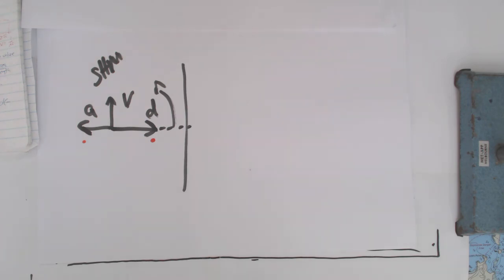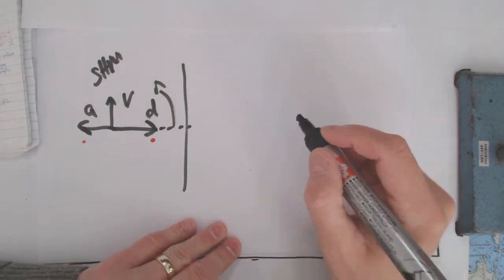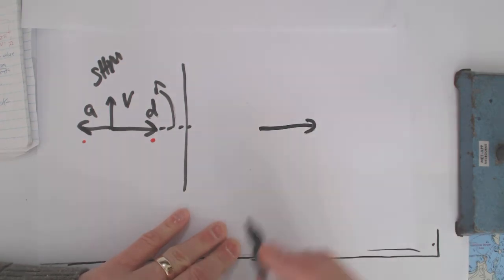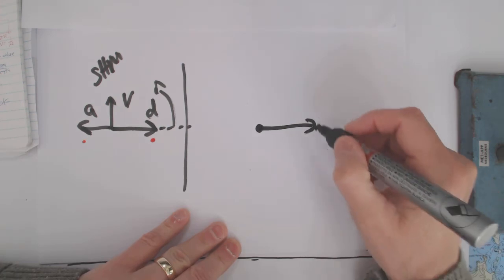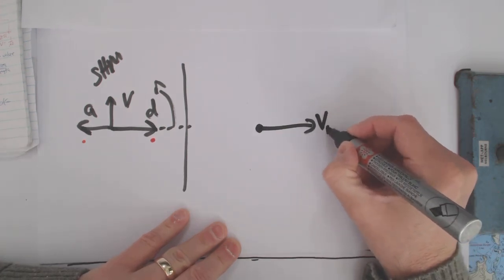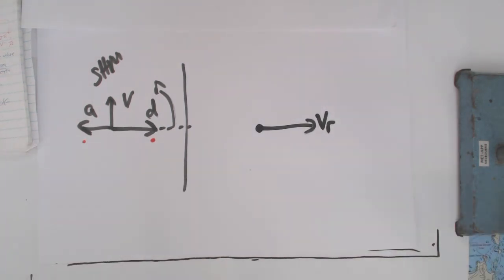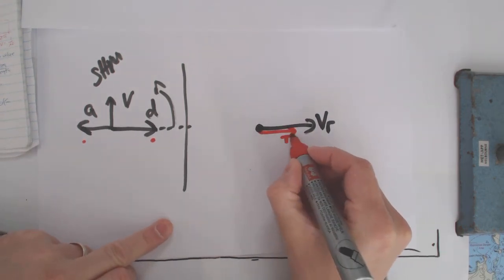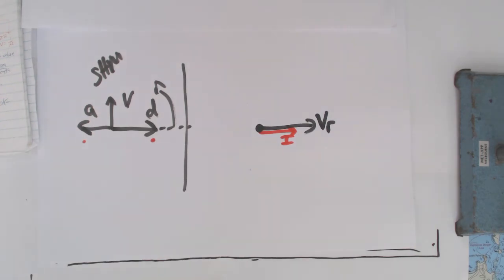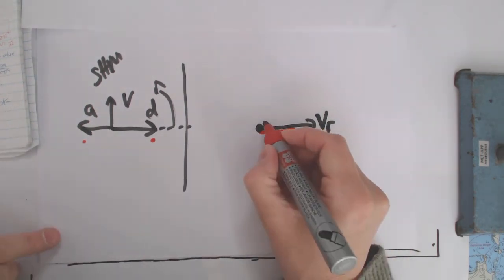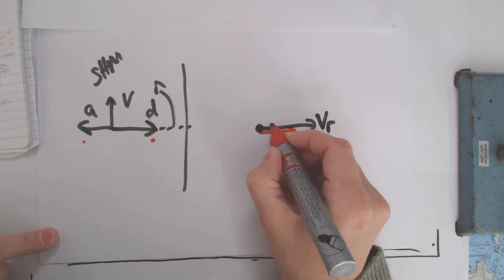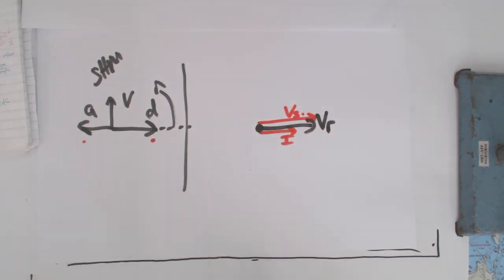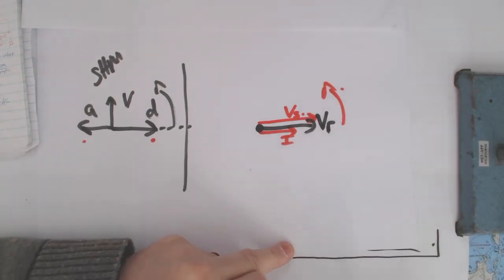So looking at it from that point of view, if we want to draw a phasor for the VR, that's my phasor for VR, voltage across R, the resistor. This is my electrical circuit now. I just said the current was in phase, so if that was my current phasor, it could be totally with that one. And I could also have my, I'll put it in red just so you can see it on top, this would also be my Vs. So they'd all be in phase going around together. And that's the way this diagram would look.